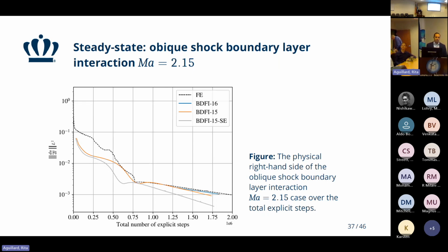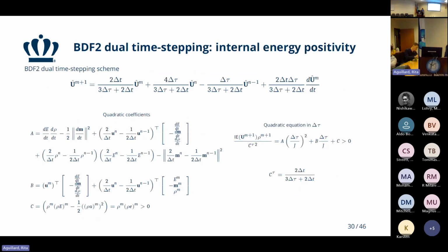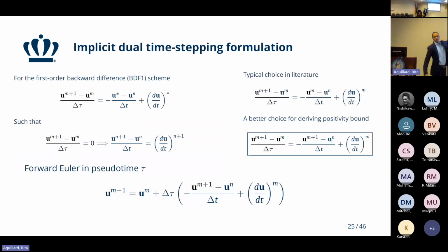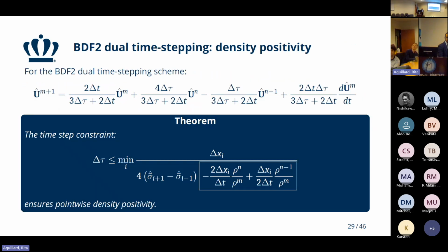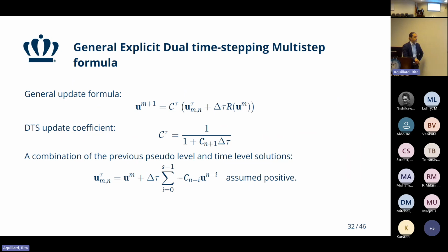And can we use the same number of pseudo iterations at every implicit time step? No, actually. We use a convergence criterion. We basically take the L2 norm of this, the absolute residual, and you require a reduction. For this case, we reduced it all the way to 10 to the minus 8 in dual time. And in other cases, we use different numbers.